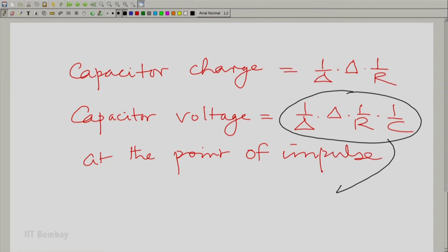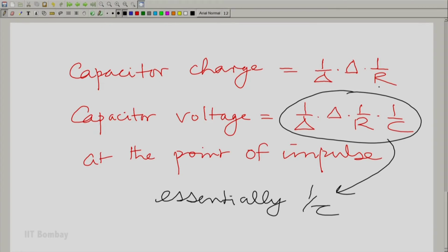And as you can see, this expression is essentially 1 by tau. So, now we know what happened. There was a charge suddenly pumped into the capacitance, so it caused the voltage to jump. That charge was equal to 1 by R. Go back here, in fact you can see that the charge is 1 by R irrespective of delta, even as delta tends to 0.